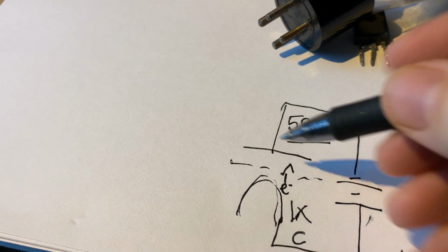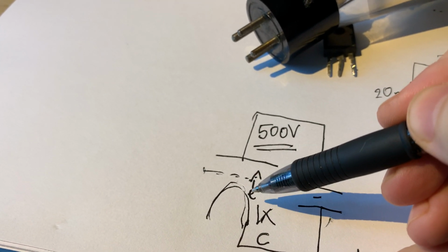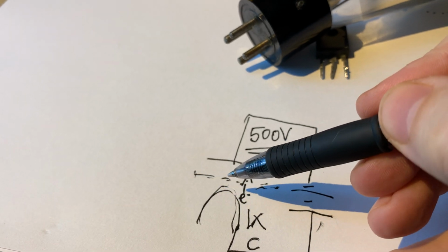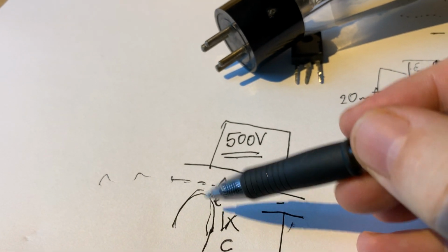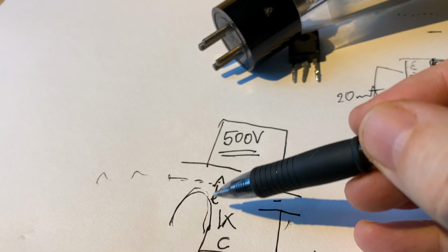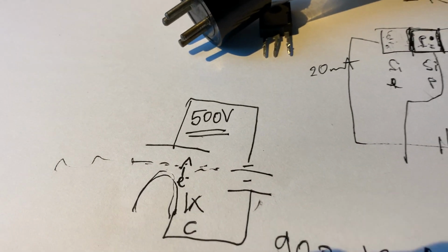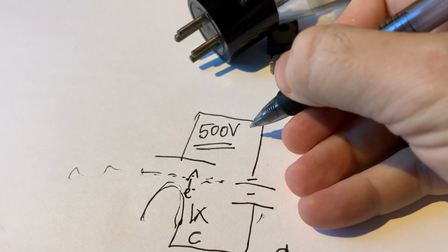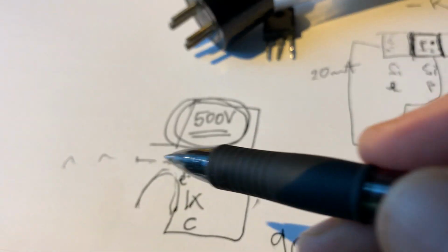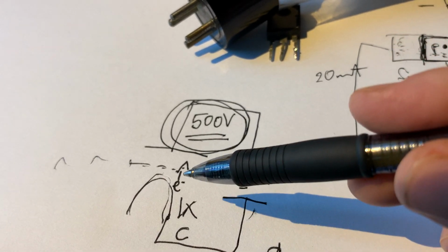And this control grid is required to have a negative charge, so that it's in the path of these electrons, and basically shields this electrode from the cathode. When we apply the music signal to this electrode, then based on the music signal, the electrons can move to the plate, or they are held here, move more, held here. As a result, we will have electrons that are accelerated to 500 volts. So a vacuum tube will generate extremely fast, very high voltage, very high energy electrons.